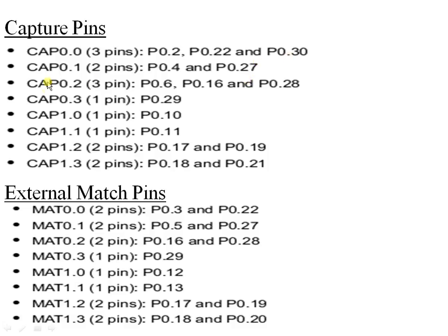Because basically all these pins will be acting as GPIOs by default. So if you want to use any one of these pins to act as a capture or counter pin, then you have to configure the pin select register. Okay.